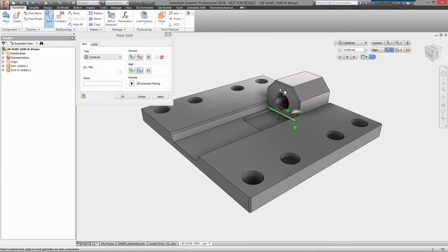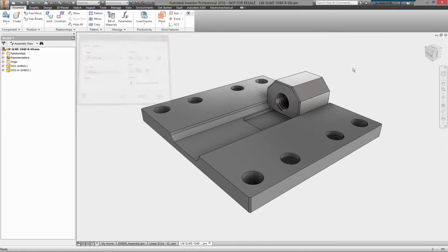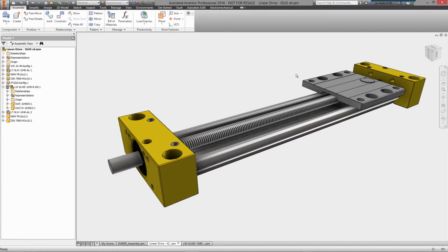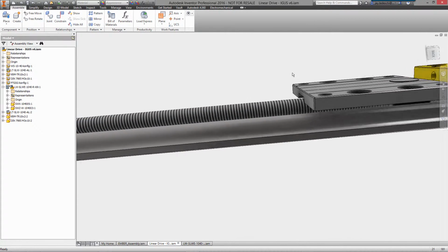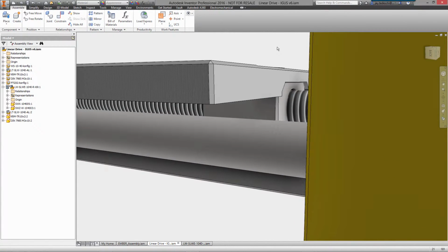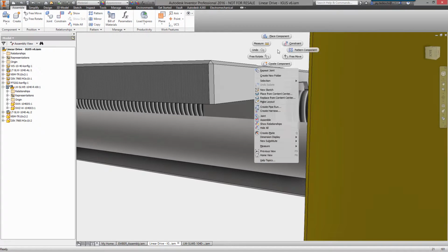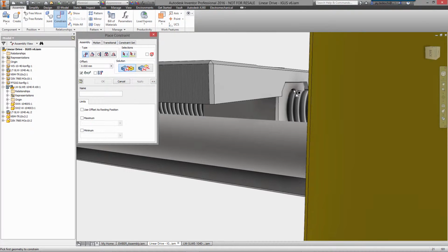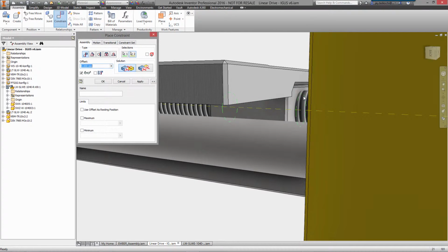However, the joints, which were introduced to Inventor several years ago, are significantly more advantageous if you are following up the design with any sort of dynamic simulation where joints are used as opposed to constraints. In the past, if you use constraints, those constraints are automatically converted to joints in dynamic sim. However, this basically eliminates the need for that if you use joints.